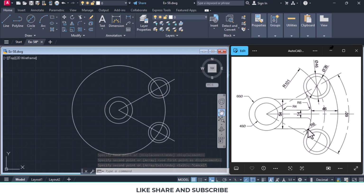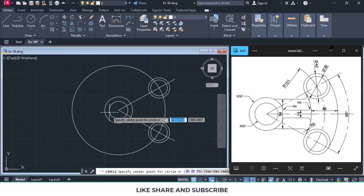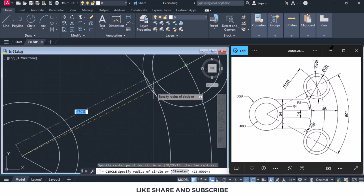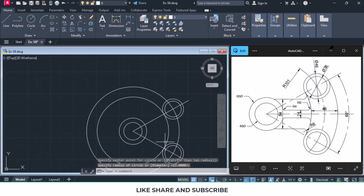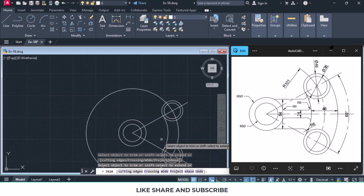Now we want to draw this arc and this arc. So we'll use circle and center radius. This is the center point, and intersection of this would be the radius. So we get this arc, and we'll trim the unwanted part of the circle. So we type trim and we click over here. So we get this arc.